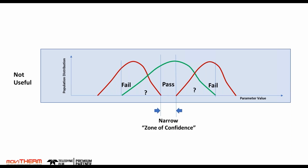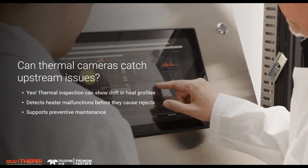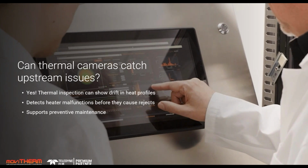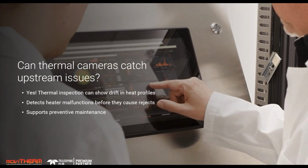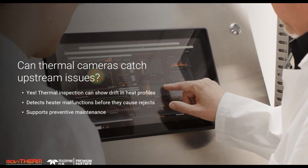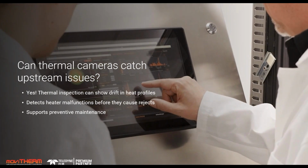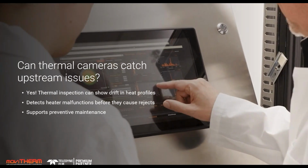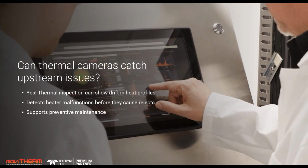Oh yeah, especially because if we're getting tight process variability, and we're starting to see maybe issues with the filler, maybe there's some product around the seal, or potentially torquing issues, those are going to really stand out, and we're going to be able to capture those, along with maybe even capping issues. And even with your induction sealer, we can potentially find issues before it gets to the point where you're creating bad seals, because we actually have a warning system as well.